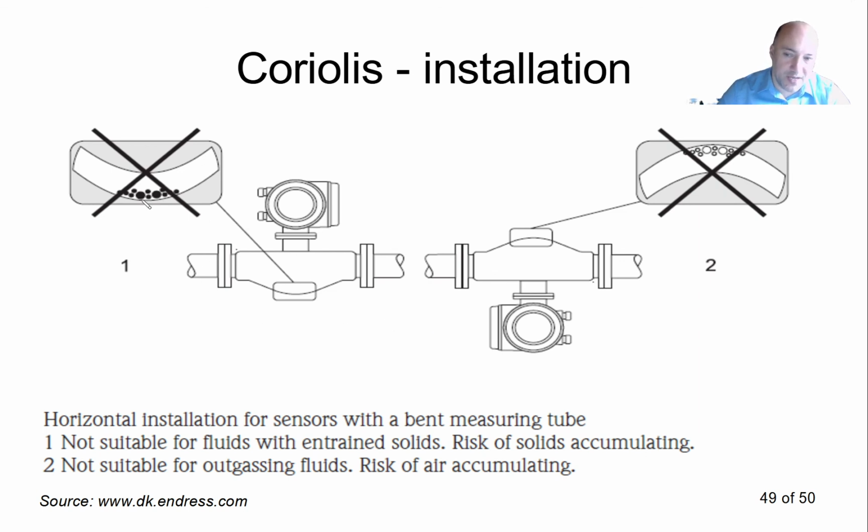If you have sediments, this is a problem. They may accumulate in the bottom of your pipe. If you have air bubbles, they may accumulate on top of your pipe. So this is not a good way the sensor should be installed if there is a risk of bubbles or sediments in your application.